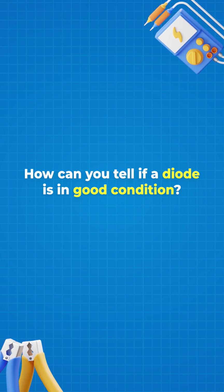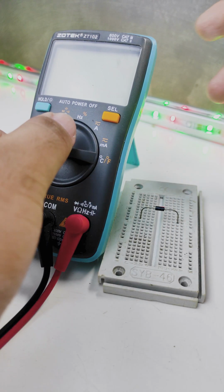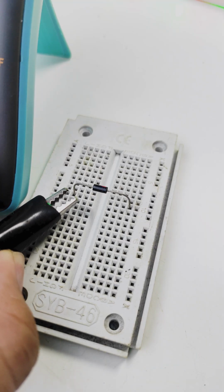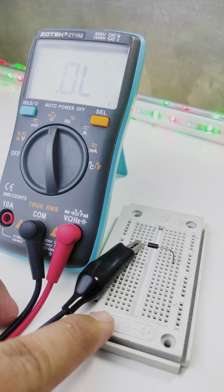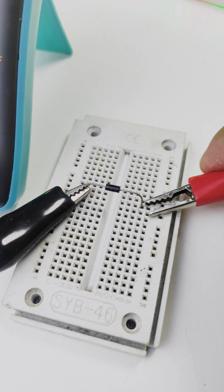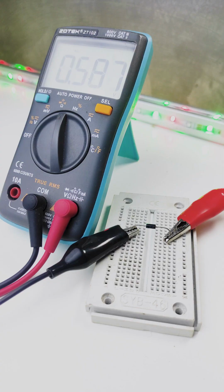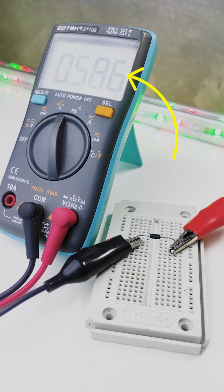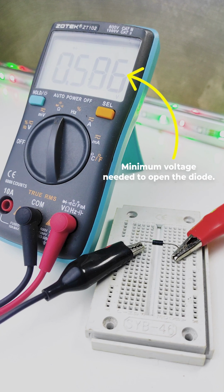Now, how can you tell if a diode is in good condition? We need a diode and a multimeter. Put your multimeter on the diode setting. After that, connect the black probe to the end of the diode with the stripe, and then connect the red probe to the opposite end. If we do that, we should get a reading on the screen. For instance, this diode gives us a reading of 0.586 volts. That is the minimum voltage it takes to open the diode and allow current to flow.